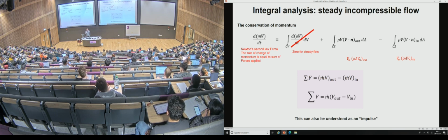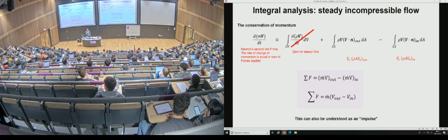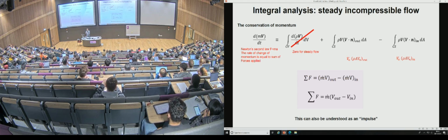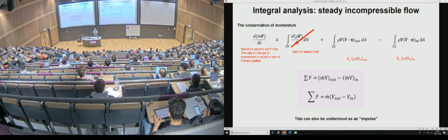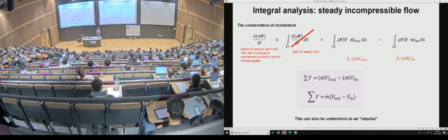So hands up if you've heard of impulse before. Excellent. That's pretty much everybody. Impulse is essentially exactly the same thing in a more general way. Impulse is a force times a change in time. A force times a change in time is equal to a change in momentum. And that's exactly what we have in this equation. The difference is that we have a mass of fluid which is changing, which is flowing with a rate of m dot, the mass flow rate. But otherwise, it's essentially the same thing.